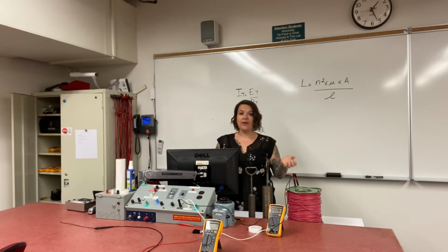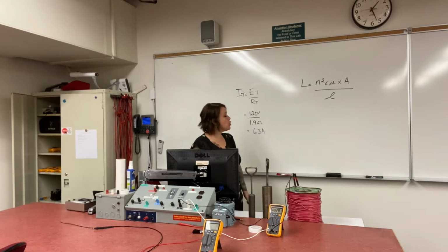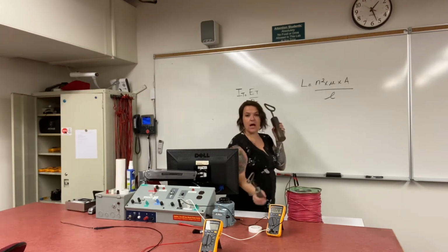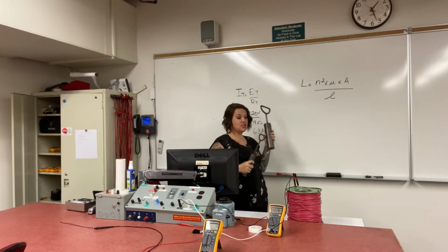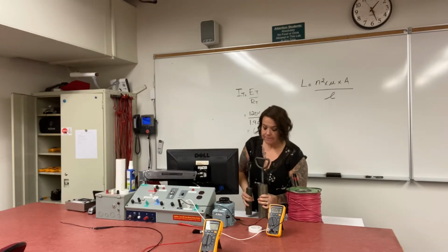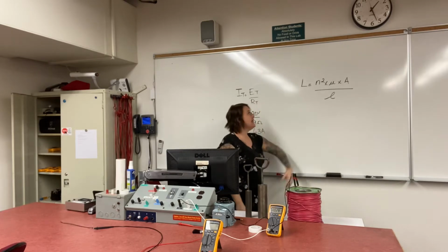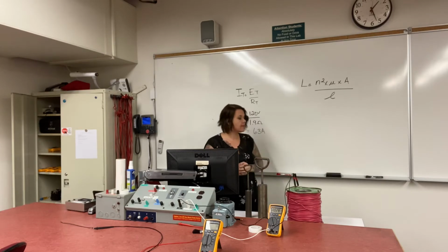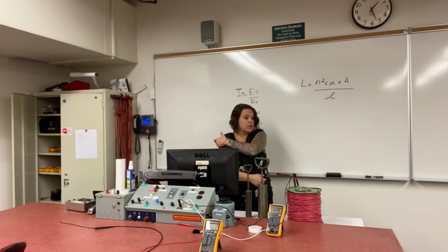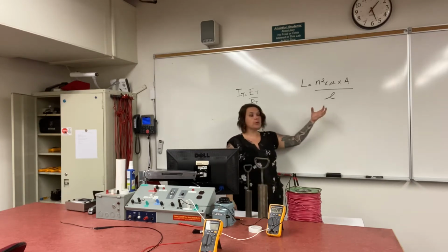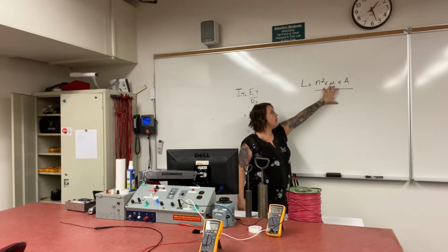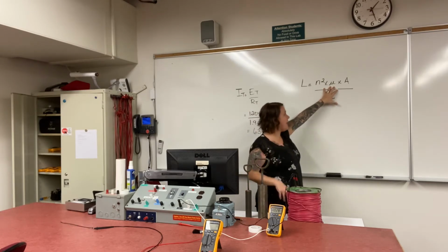So when I initially energized this coil of wire with our 8.2 amps generated, I was essentially using a coil with an air core, right? So I can change that core by inserting these iron cores and thus changing the amount of inductance that's created in our circuit. And with changing of the inductance value, we're affecting the overall current, okay? Permeability is the ability of our coil to generate lines of flux, and that's changed by the type of core we have.